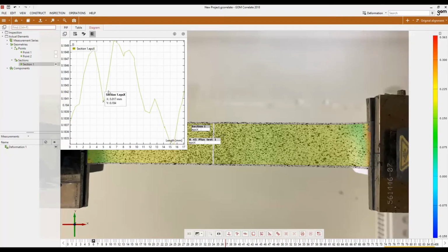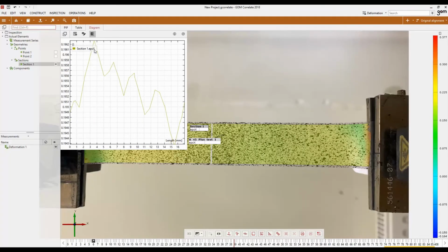And we would see that along this curve at this given time or given displacement, the strain is not a constant straight line. It fluctuates as minimum of 0.1835, maximum of 0.1849. It's not much, but it is there, some deviation. If we want, we can again export, but if we do that, we have to remember that we will get the strain as a function of this length only at a given time where I asked this curve at.